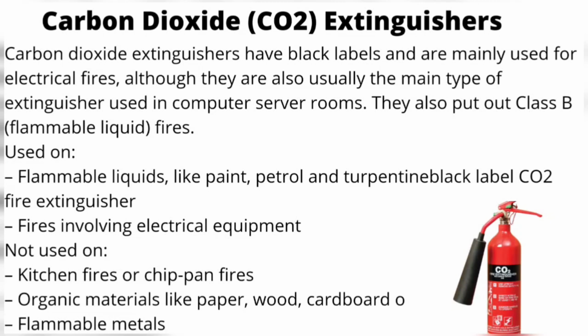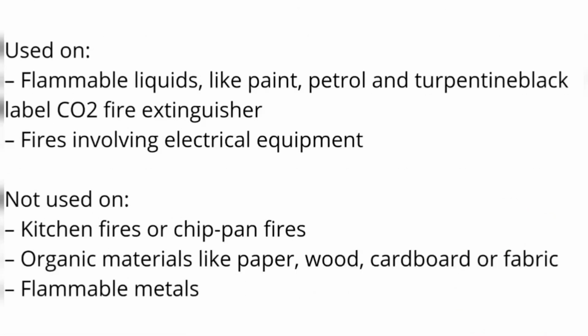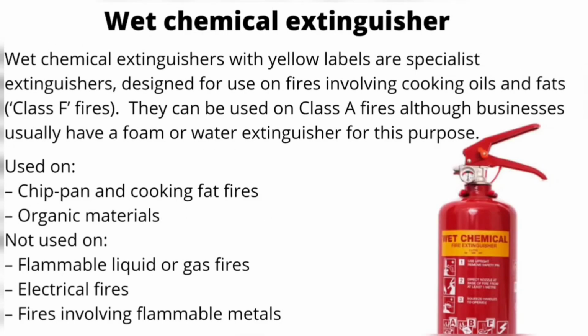Black label CO2 fire extinguisher. Used on fires involving electrical equipment. Not used on kitchen fires or chip pan fires, organic materials like paper, wood, cardboard or fabric, flammable metals.